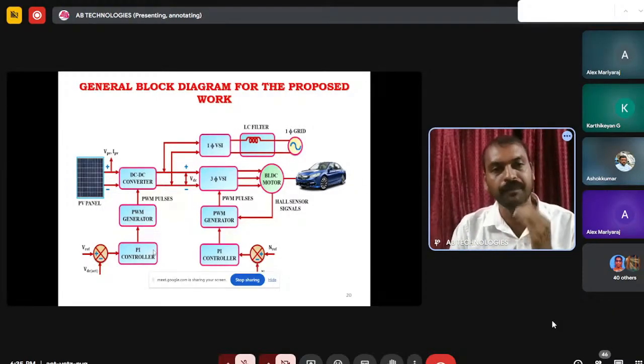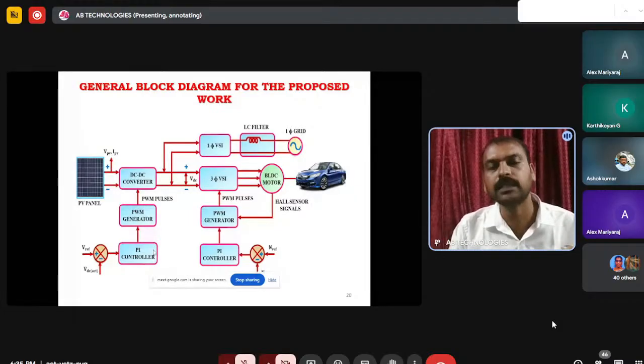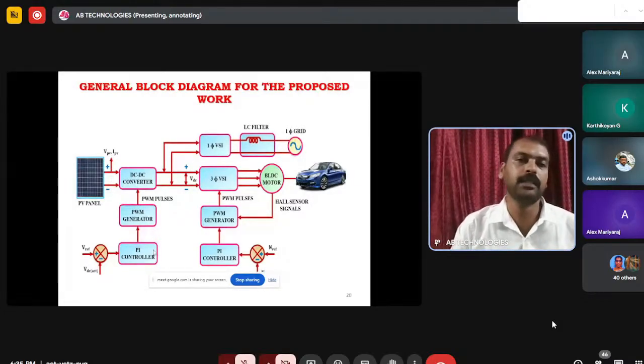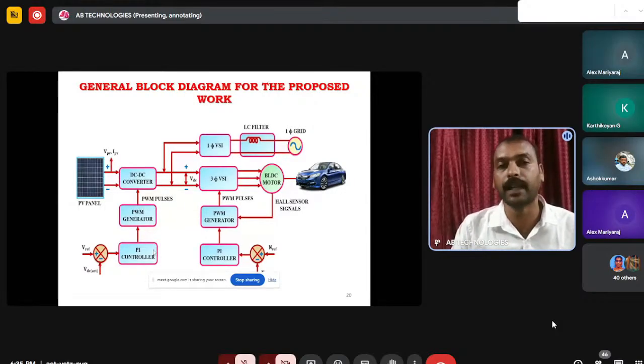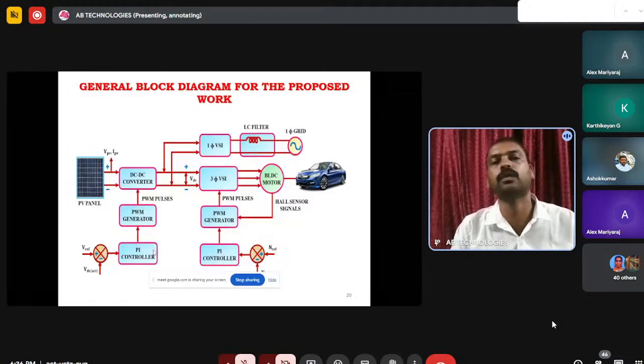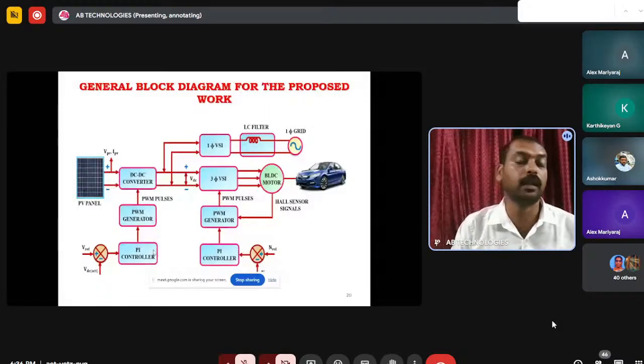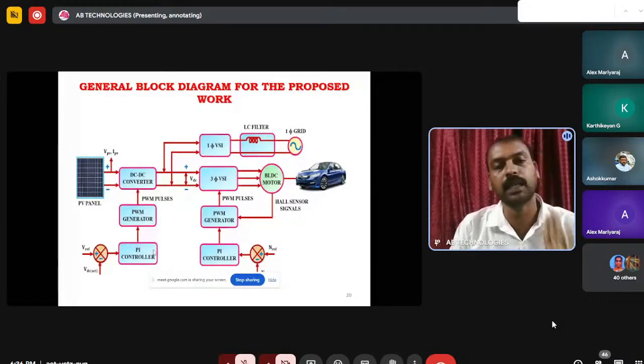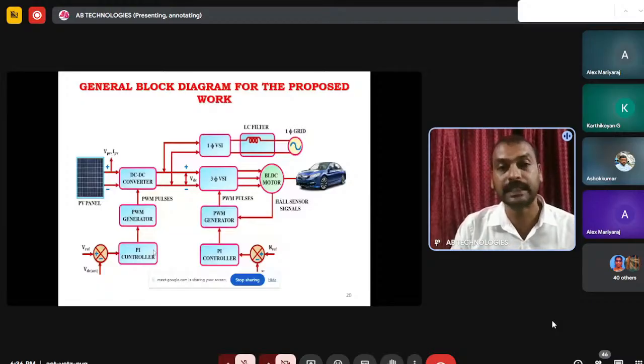And the second one, the function of the inductor. We know the basic concept of the inductor. It is an energy storage element. That means it stores energy in the form of electromagnetic energy. So for example, if you provide a 12 volt input to the boost converter, you will get around 18 volts, but you have to maintain nearly 98% duty cycle of the converter. That means switching stress as well as switching loss is very, very high.